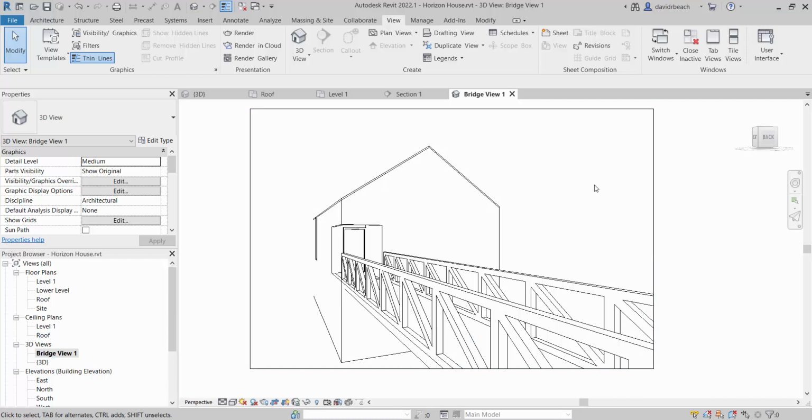I see this as the quality of line drawing all the time in architecture school, and it makes me crazy. Because fixing this, making this look a lot nicer is just super easy, you guys. And what I'm going to show you is very formulaic, but it works very well. So right down here at my graphic display options, I want everybody to activate graphic display options. And let's go through this list.